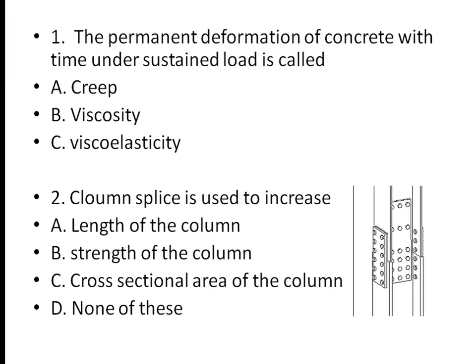And the second question is column splice is used to increase. This is a column splice, and it is used to increase the length of the column. It is used to transfer the load into the foundation and it is placed 1/3 or 1/4 of the column.